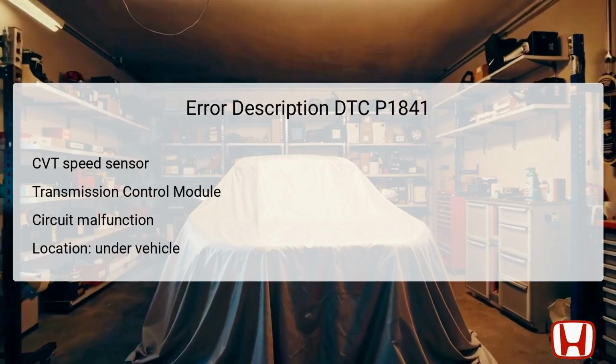The P1841 error points to a fault in the CVT speed sensor and its relation to the TCM. The CVT speed sensor plays a critical role in monitoring the rotational speed of the secondary shaft, which is vital for optimal transmission performance, especially in reverse mode. This sensor's readings are communicated to the TCM, which uses this data to adjust internal settings for the transmission operation effectively. The CVT speed sensor is typically located on the transmission assembly under the vehicle, making it accessible for inspection.